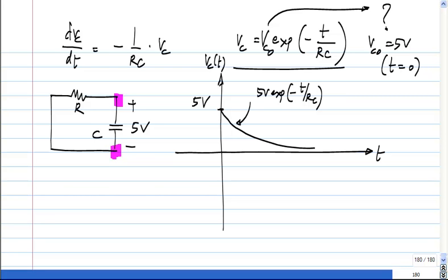So, that's why what happens is it starts falling, and then the rate of falling becomes shallower and shallower until finally it reaches 0, but only at t equal to infinity. Okay. That is known as asymptotically reaching some value. That is, it will not reach that 0 value for any finite value of t, but only for t equal to infinity. Okay. So, you should know both these, like how to solve for this is after all a very simple equation. At the same time, why it comes out the way it is, that you know from the circuit that the current in the capacitor keeps on falling. Okay.